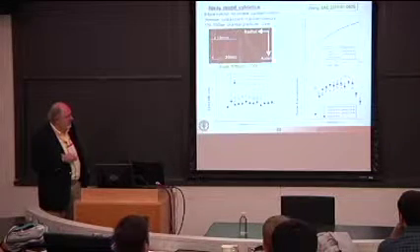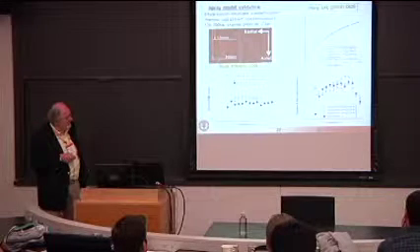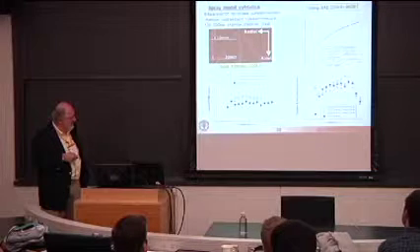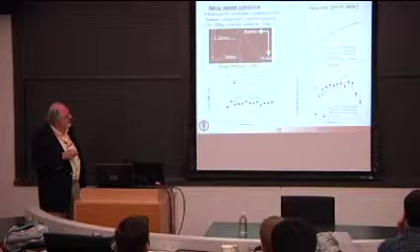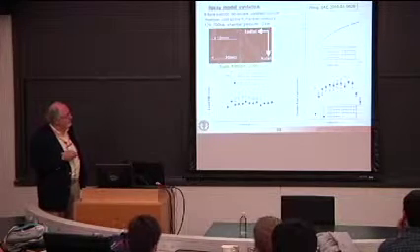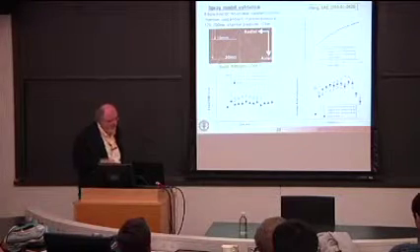This is the velocity of the droplets, which the PDPA instrument is also able to provide. You can see fairly good agreement between the solid measured data and the symbols with different mesh resolutions. And then here is the tip penetration as a function of time, spray penetration typically. And you can see, at least in the range where the measurements are, pretty good agreement.